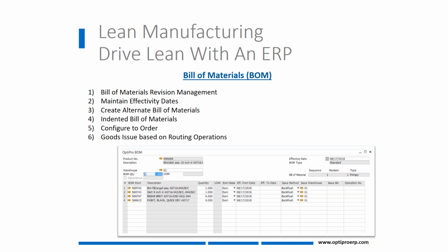So things like effectivity dates. I've made a change in a sub-assembly, and therefore, I have to use up what I have, or I have to rework what I have, and I'm going to phase in the new revision. We have to be able to manage those effectivity dates.